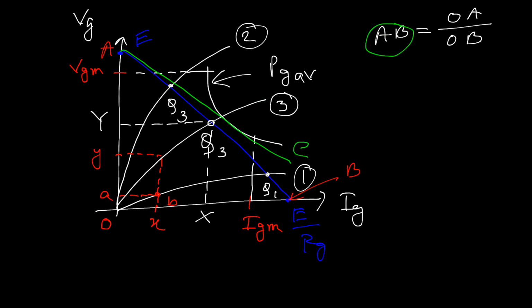So this is all about the gate characteristics of a thyristor. Now, since the thyristor is a current and charge controlled device, if the magnitude of the gate current is increased, the time taken to inject the required charge for turn-on of a thyristor will be reduced significantly.